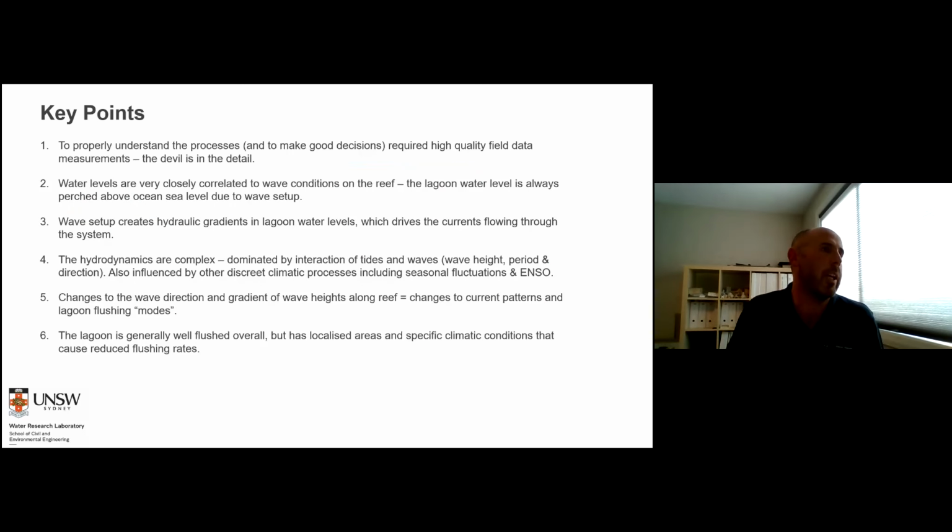So I guess some of the key points that we took out of doing this kind of work, given that it's so complicated and it's not a typical system like our estuaries where you have tides really driving the flows in and out, this is something where tides play a role in modulating the system, but it's really driven by wave energy and wave setup processes. And to really understand how the hydrodynamics are working, you really have to understand from field data how the water levels are all sitting relative to each of those bathymetric features in the lagoon and how the whole system's fitting together.